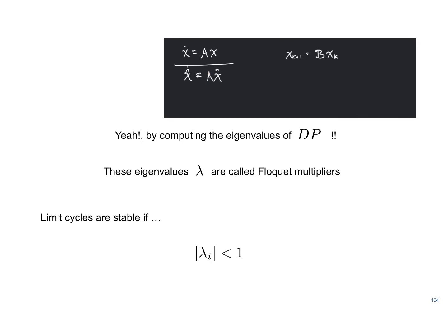And you know also that for an ODE, you have this kind of solution. So I will just write the eigenvalues lambda, okay. In this case, you can observe that the stability of the perturbation is given by this lambda, in this case the eigenvalues of A, and they must be negative, so smaller than 0, so that this perturbation goes to 0, which means that the system is stable.